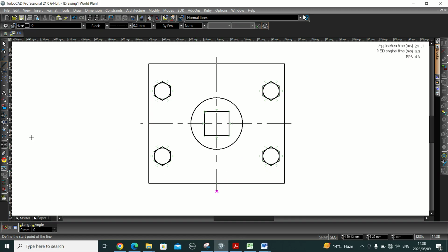All right, now go to your line tool, make sure it's selected, change the line properties to hidden detail, make that to be 0.5. We want to draw a line starting from this point here. Press tab. X will be highlighted. We said x is 30, y is negative 44. Press enter.